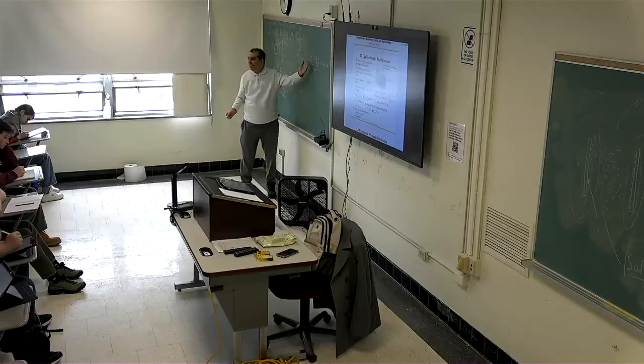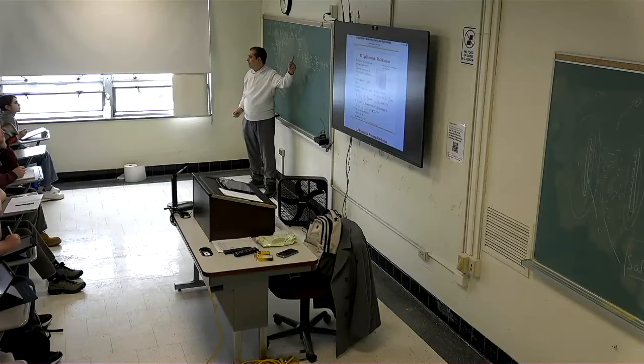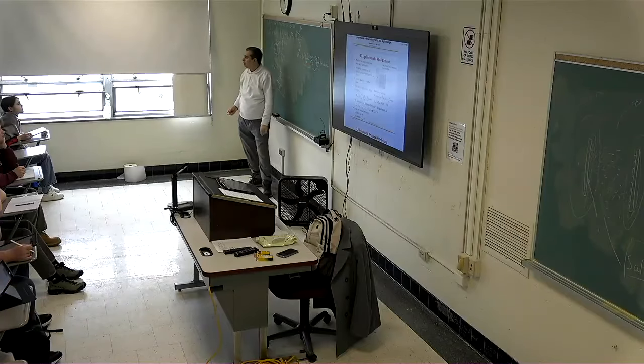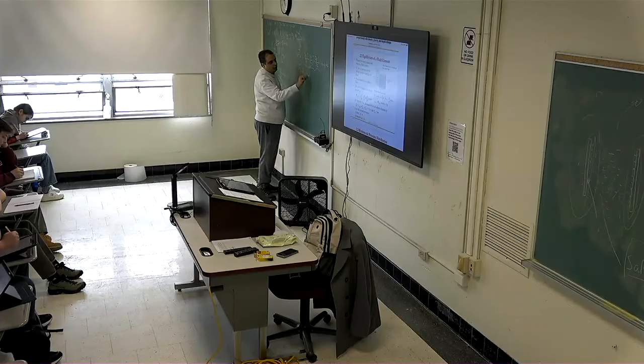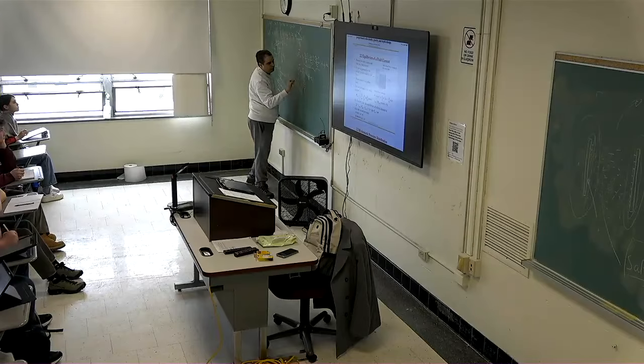What is the name of these three together? From mathematics: partial p partial x i, partial p partial y j, partial p partial z k. Gradient. So dF is minus grad p delta x delta y delta z. dF per volume is equal to minus grad p.